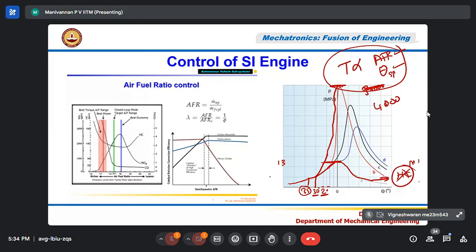Correct. You adjust the spark advance: 21 degrees, 20 degrees, 23, 24. Set the engine RPM to 4000 RPM in the dynamometer. Then maintain the air-fuel ratio at 15:1. Then change the spark timing in the test bed. You will do this in the dynamometer in your company. That is what is called the spark timing map and air-fuel ratio map. You have to develop that. It will take 6 months to develop and put into a commercial vehicle and run it. That's the job of you.